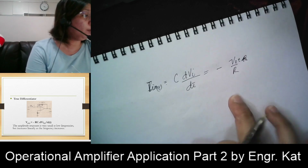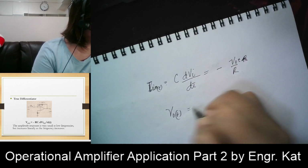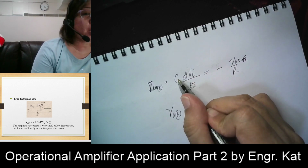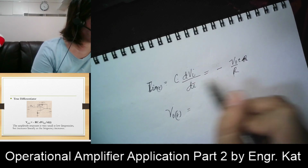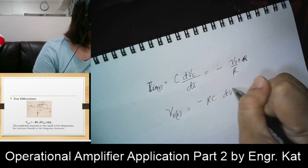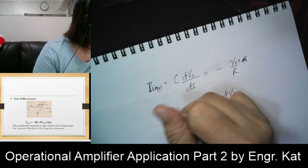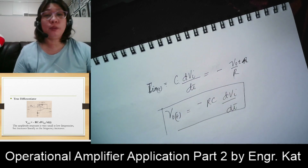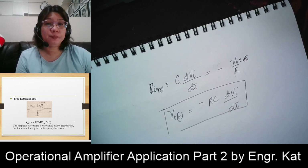Okay, so solving now for your output, we can place your R here and cross multiply your R there. So we have minus RC multiplied by dVI all over dt. So this is our formula, our output formula for our true differentiator circuit.